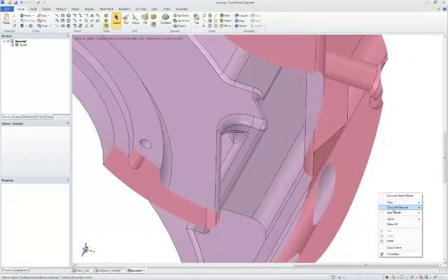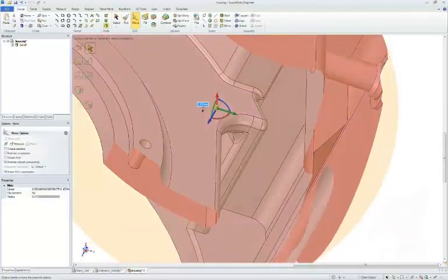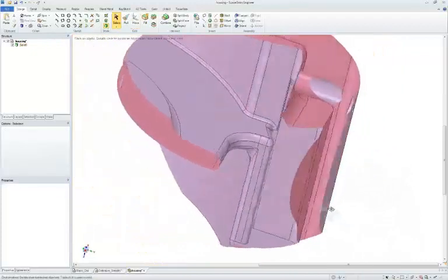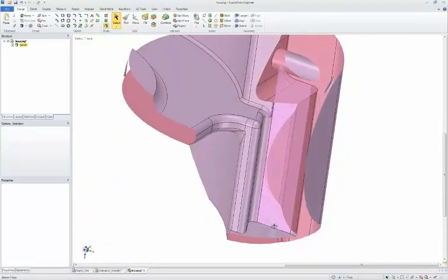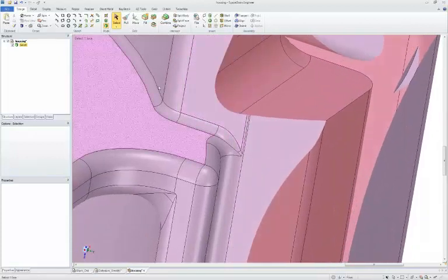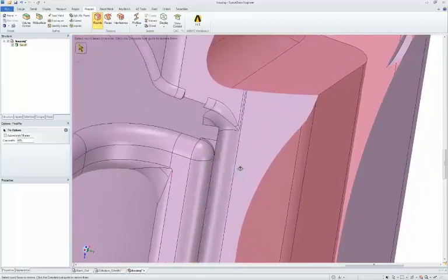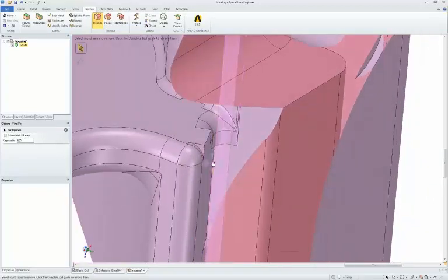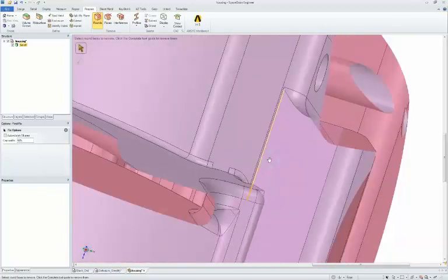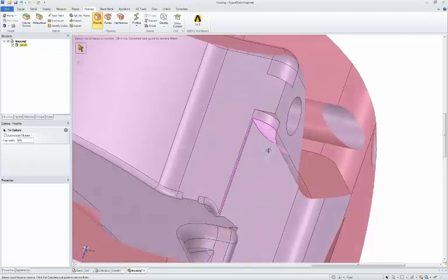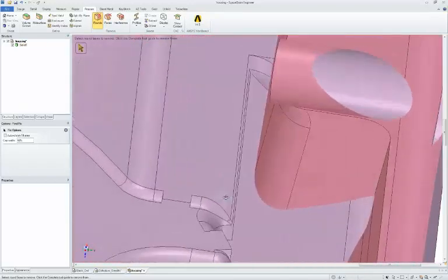This can definitely cause a problem because there's 2 really small faces that are going into a third face. This is something that I definitely want to take care of and eliminate in the model. This is a perfect example of that round tool, specifically designed to slice rounds up and subdivide them and get rid of anything you don't want on the design. So now that I've eliminated this, no problem.